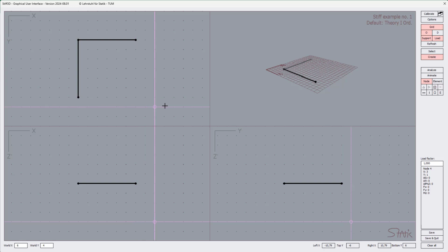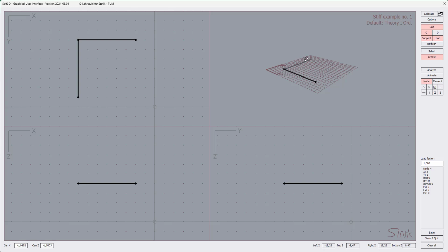Good. So to come back to our structure, we have now the top 2 bars. I would like to create the column, and then we come to the specific definition of the z coordinate here in Stiff. That's related to our lectures where, let's say since ever, the z coordinate is pointing downward along gravity. So at the roof of the structure, the z has a smaller value than at the bottom, at the foundation. And to create the z aligned column pointing downward, we should attach that here to the cross point there.